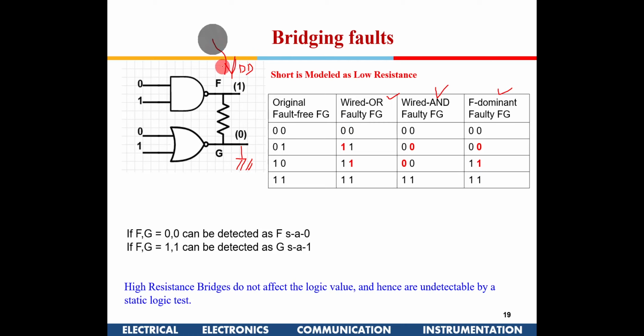So that means it is not directly connected to VDD, right? It is coming through some PMOS. So if this PMOS can provide much higher current than the NMOS, which is sinking this current, correct? If the current coming from the PMOS is much more than the current being sunk at this ground by this NMOS. This NMOS is coming from this particular circuit. This PMOS is coming from this particular circuit.